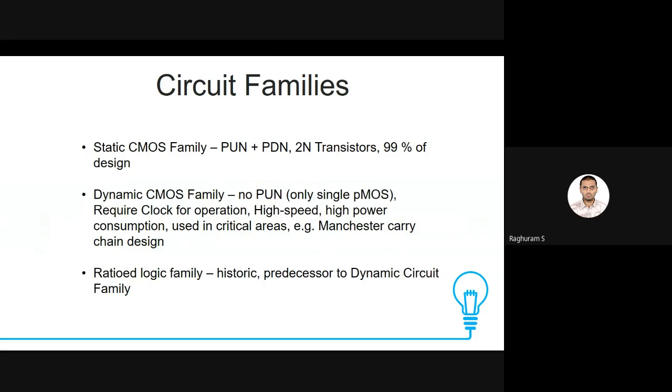some particular path in my design, and this is forming the critical path. So when you are generating that timing report, right, there are some gates which are part of that timing report. Suppose the timing report is, say, 700 picoseconds, and it is the best you can do with static CMOS circuits, but unfortunately the requirement is 600 picoseconds. But we have got the best circuit, we have done everything we can from our side. Then we have an option of getting one extra level of improvement if we change the static CMOS.